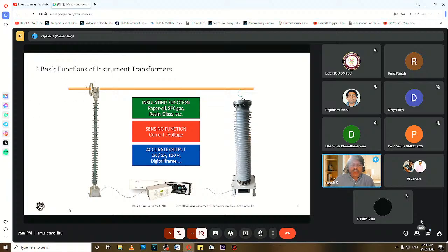When you have a flux, there will be polarized light being sent in the donut core, and you can imagine it weighs hardly 15-20 kgs. A conventional CT core weighs hundreds of kgs plus. So it's only insulation which is required. Otherwise, you can use a simple mechanism like a donut optical CT sensor, what you see on the left side. Similarly, on the right side, we have a VT. Then the output from the device will be proprietary data, which will be on optical.